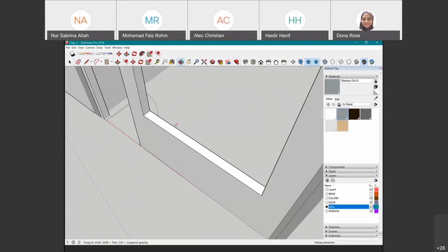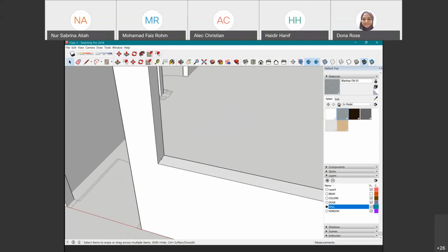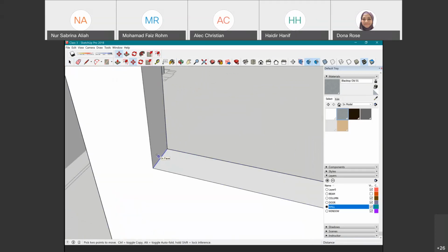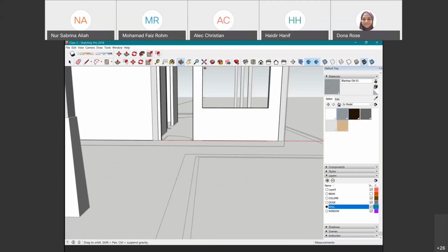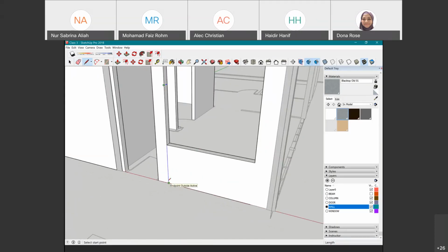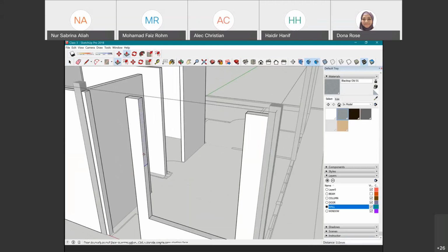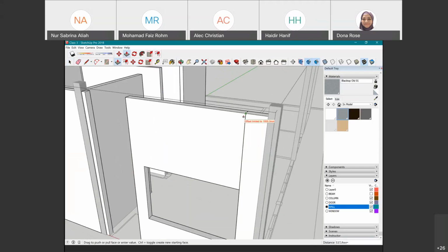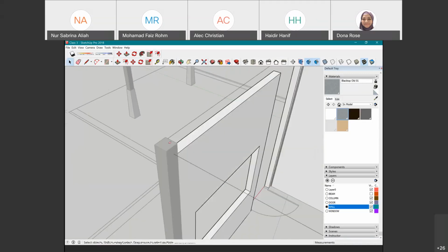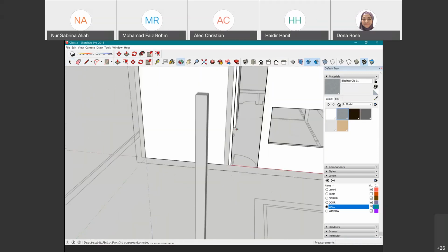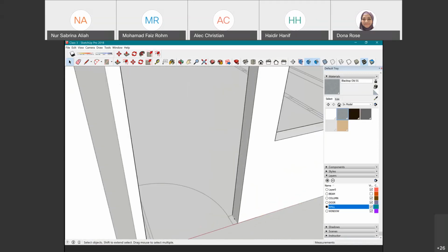And then let's say if you want to have the window, how high? So this one I move. This is how I do it. I move and then I press control, move. Let's say the window height is 1200. And then like that. Okay, to make an opening. But I don't recommend it because there will be a lot of work. Same for this opening.